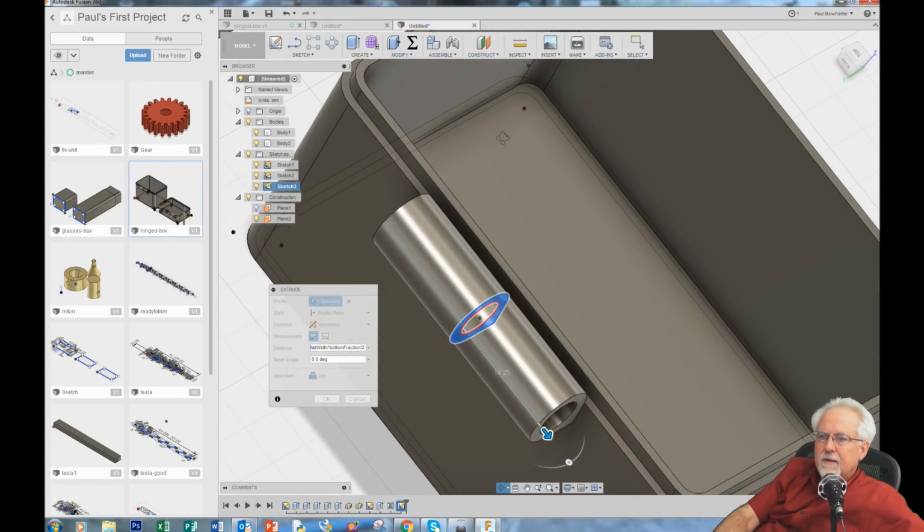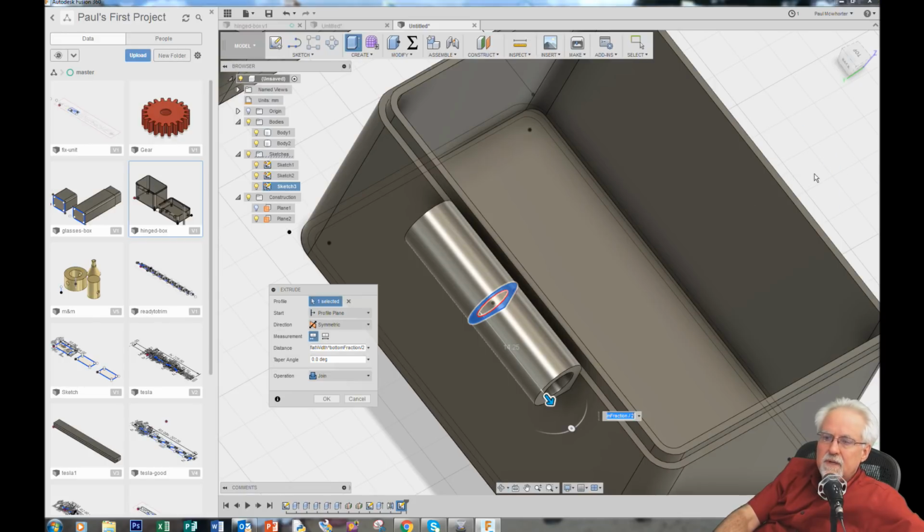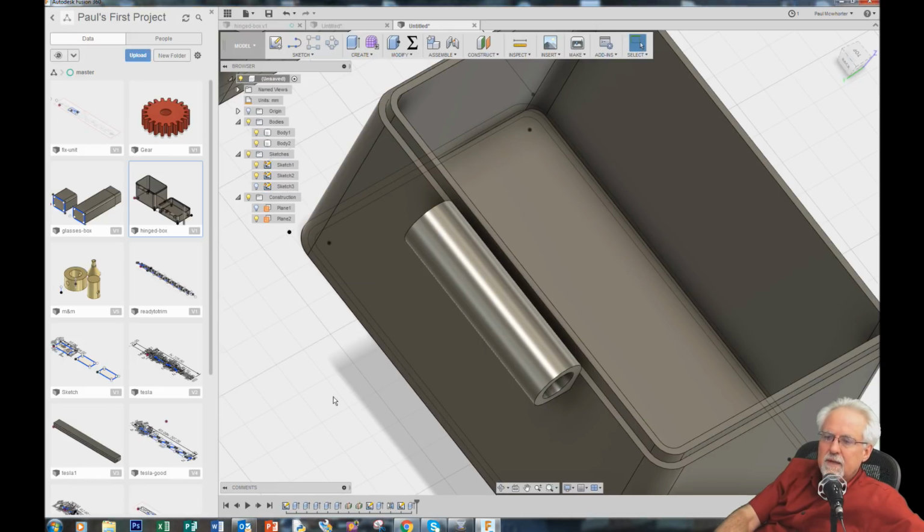Remember the flat width was from right here, the edge of the round to the edge of the round. That's the flat width. How much of that can I use on the bottom? The half width times the bottom fraction. Then I'm going to come out that much here and that much here. Coming out this way, I can only use half of it, and that is the reason for the divide by 2. Does that make sense? There are a lot of different ways that you can define this, but you just want to do something that's going to work. And then I can say okay.